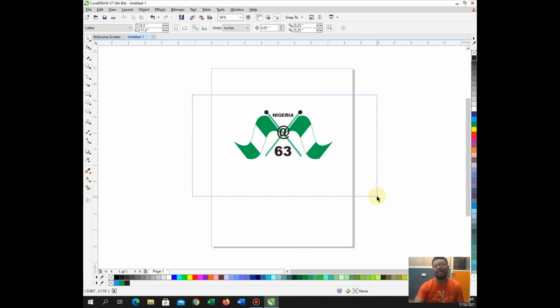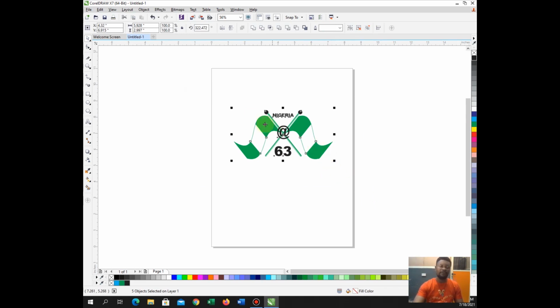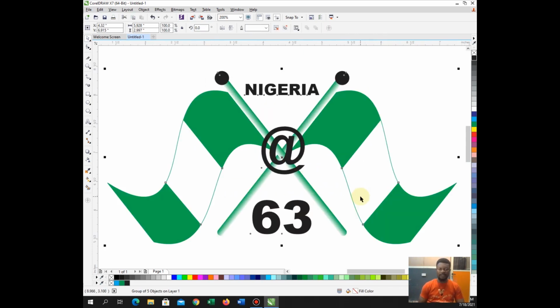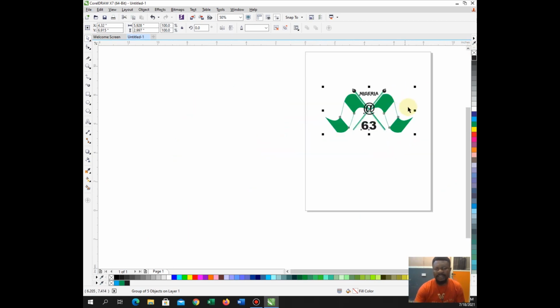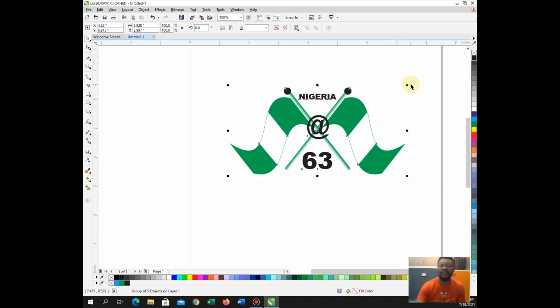So with this now I have designed my stuff. So let me group it. I select everything by clicking and dragging over. Then I say Ctrl G. Now F4 to see. Then F9 to see it clearly. All right. So now that is it, and that is the end of the class.